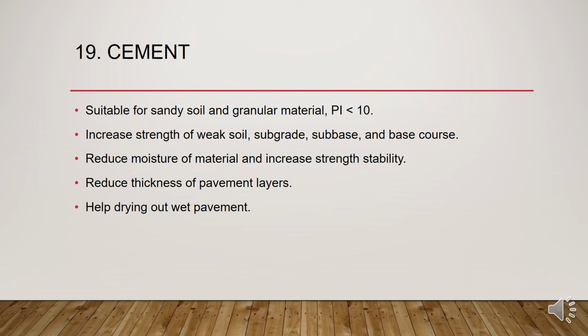It reduces moisture of material and increases strength stability. Also, cement stabilization reduces thickness of the pavement layers, and cement stabilization also helps drying out of wet pavement.